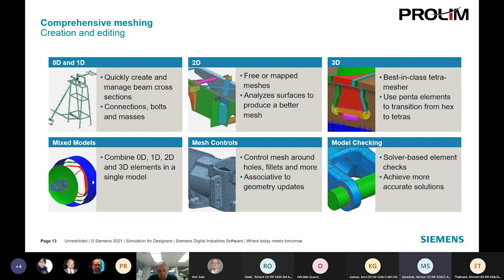2D meshing is where you may have, like we talked about, the sheet metal parts where you would do the mid surface for that, or you could also use what we call a mapped mesh that will help guide the 3D mesh to small blends, certain areas of the model that you want to refine. And then for a designer, many times you might be working in mixed models, right? You need a little bit of each of those mesh capabilities.